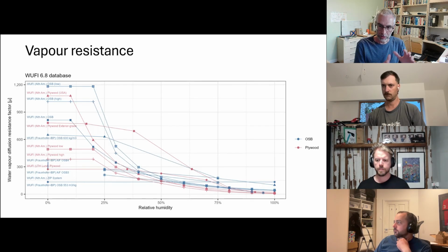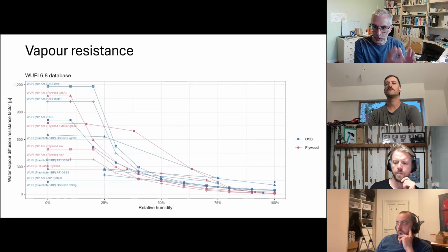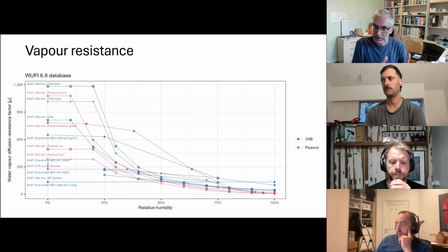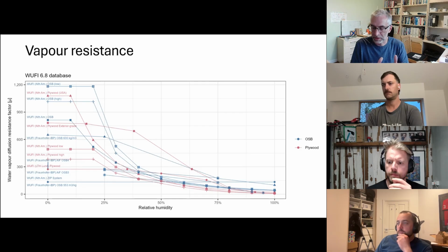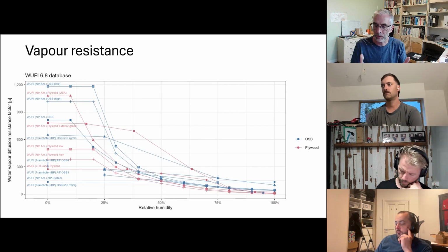And what I would argue is that what's happening at the low relative humidities doesn't really matter. If your wall is dry, who cares how vapor permeable your membranes or materials are? There's no water to get rid of. It doesn't matter. What matters is when the system gets damp. Say at relative humidity up from, say, at least 60%, maybe closer to 80%, when there's a risk of mould accumulating, of condensation forming on surfaces. At that point, it's critical that your layers have appropriate vapor permeability.